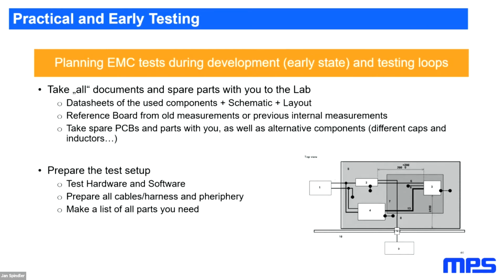Also some simple things, but I think you quite often see them: bring datasheets, schematic, and layout together to the EMC lab to be fast. When you see the problem, you can react to it. You can discuss, you can put it on the walls, you can draw something inside. You can work, you can be creative.